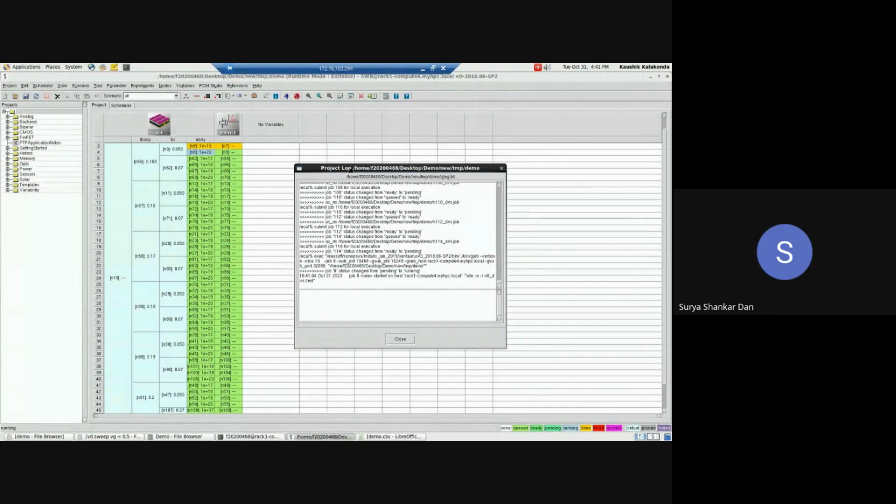So, in the long run, after 10 days, the amount of data you have obtained will essentially save a lot of your time. Remember, in this Synopsys workbench kind of batch processing, the tool will not be wasting any time at all, since you have given the whole bunch of simulations at the same time. This is going to be way better for the performance as well as the total time taken, rather than running them individually.